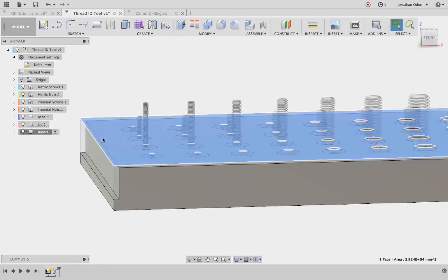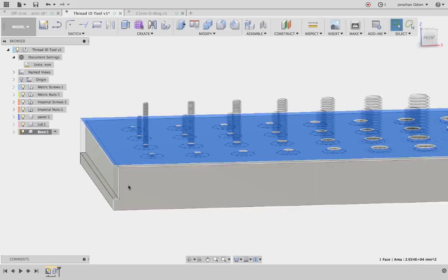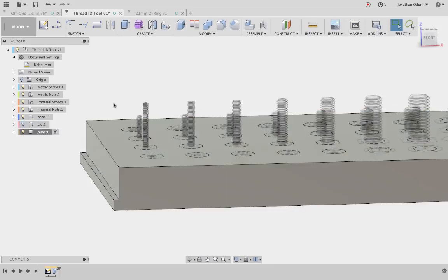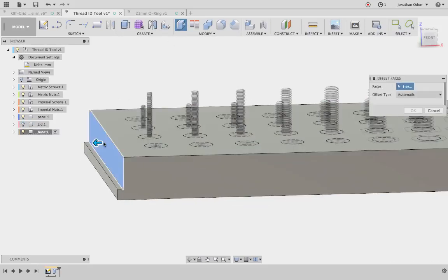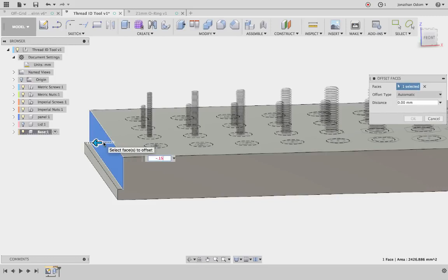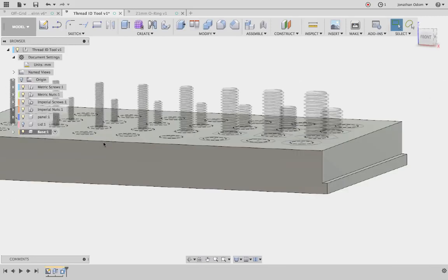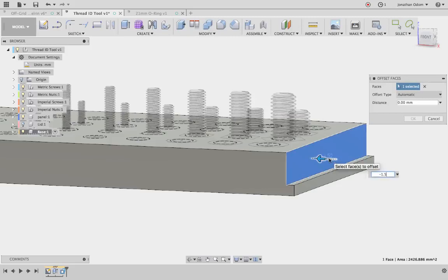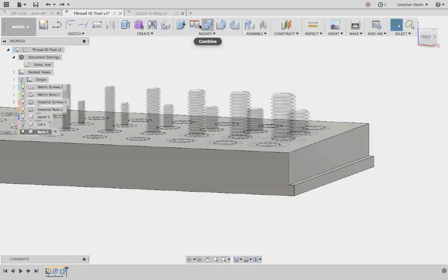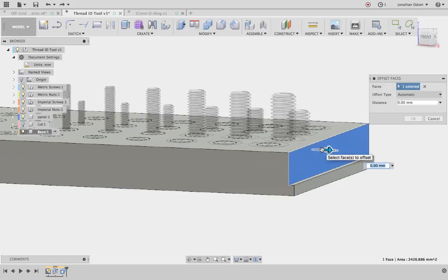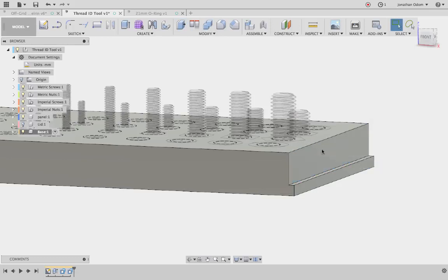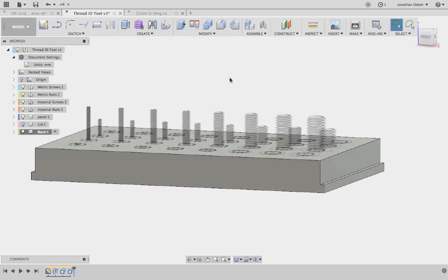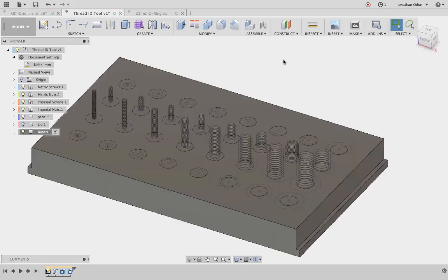And then since these parts are going to interlock, I'm going to need to give myself some tolerance for this thing down here, on the sides particularly in this case. So I'll pick that, turn off the lid, and then I'll press pull this by minus 0.15. That's a dimension I've tested on my printer that works really well for things that need to fit. Whoops, it's too far. Press pull that minus 0.15. I know that tolerance works for stuff I've done. All right.